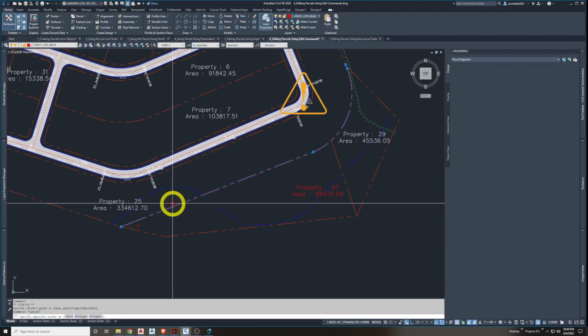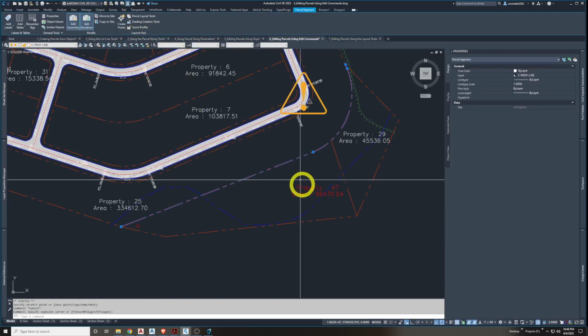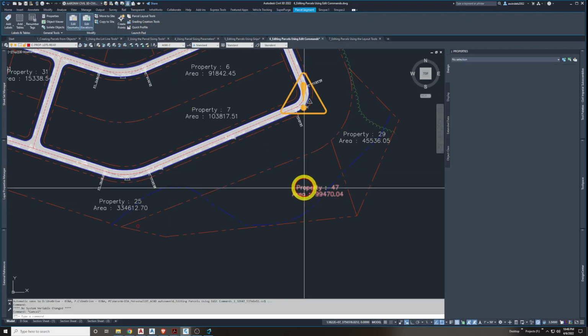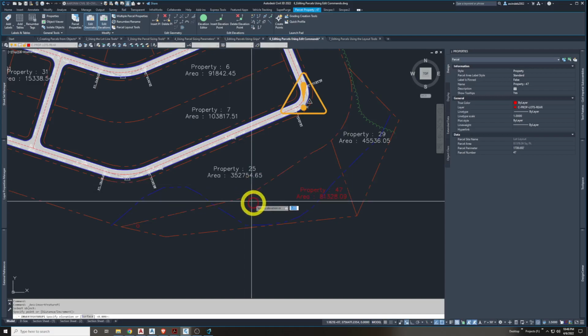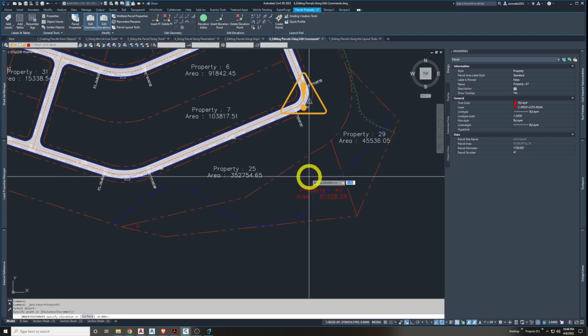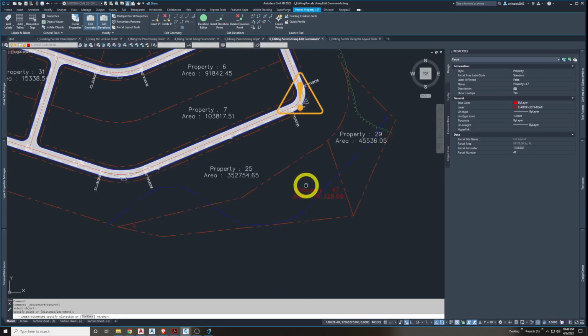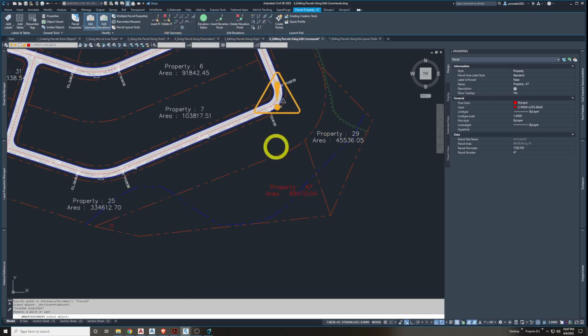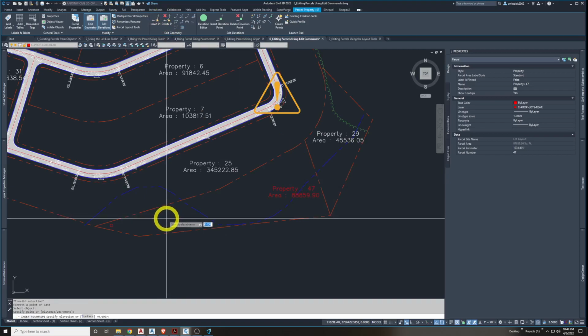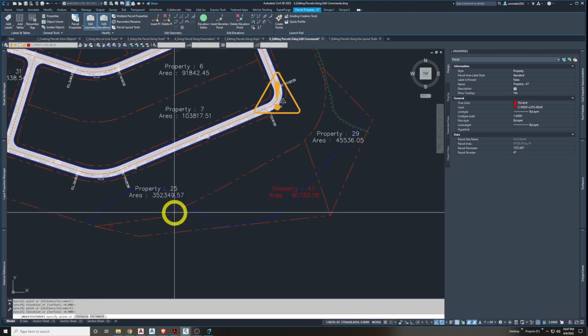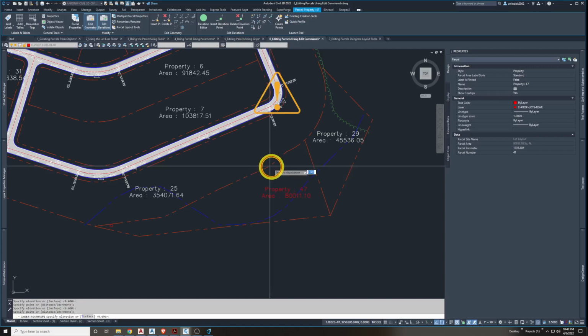Okay. I might go into this parcel segment. I'll click on the parcel object first. I might say insert PI. Do it again. Enter. Do a second one, hit enter. Do a third one, hit enter. And we can take those out again.